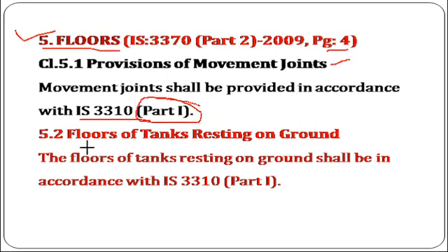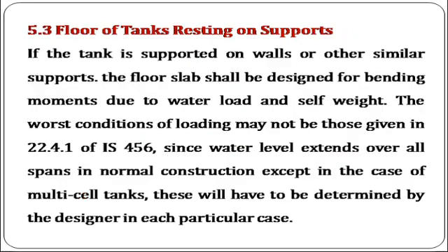So 5.2, floor of tanks resting on the ground. It is mentioned here that the floor of tanks resting on the ground shall be in accordance with IS 3370 Part 1. Again 5.3 shows the floor of the tank resting on the support, that is ground support most of the time.